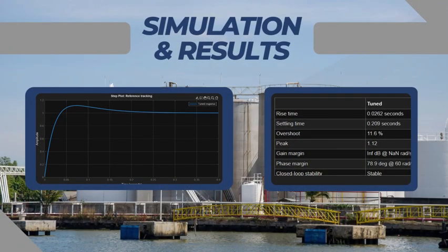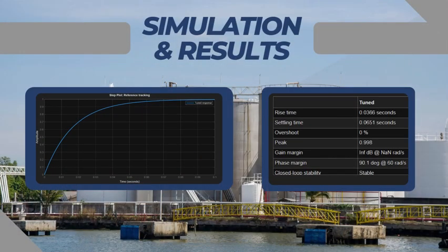4.2 Step response simulation. Step response is an analysis that shows us how the system will respond in the event of an immediate change, such as turning on a pump. 4.3 displays the response of the PID-controlled system and displays values such as rise time, overshoot, settling time when using a PID controller, proportional integral derivative, to control the water level in a water tank.